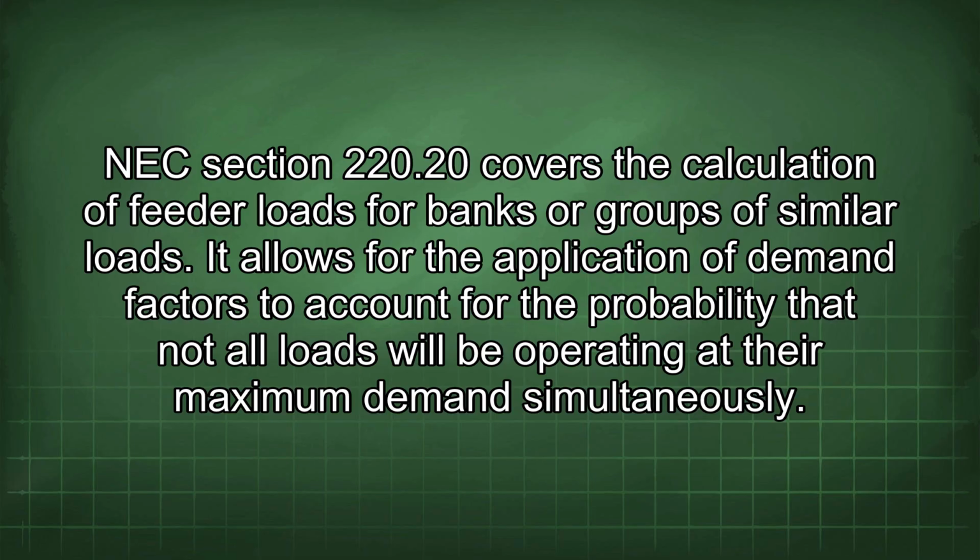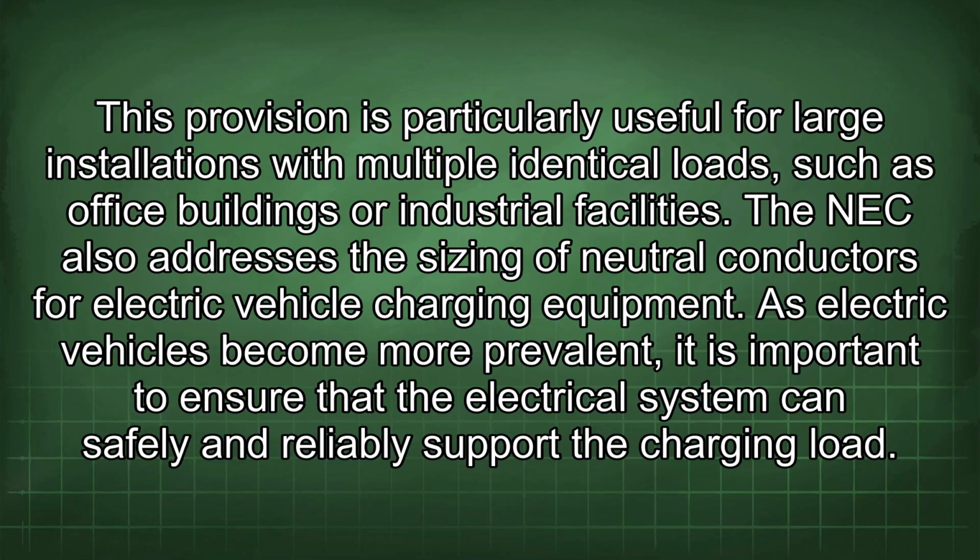NEC Section 220.20 covers the calculation of feeder loads for banks or groups of similar loads. It allows for the application of demand factors to account for the probability that not all loads will be operating at their maximum demand simultaneously. This provision is particularly useful for large installations with multiple identical loads, such as office buildings or industrial facilities.